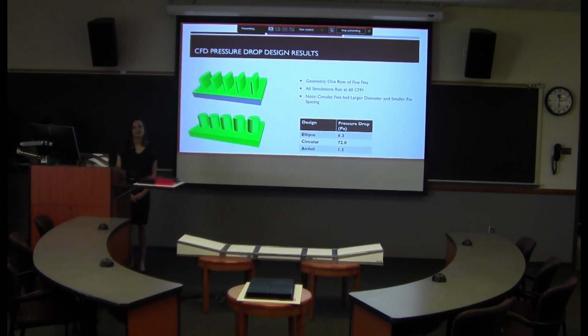Hi, my name is April Huffman, and I was the other member of the computational fluid dynamics team. And as Max said, I'm going to be walking you through some of the results of our designs. So for our designs, we decided to run models through CFD with different fin shapes and sizes to see how they compared against each other to pick the optimal design. Some of those were ellipses, circular fins, and airfoil fins.